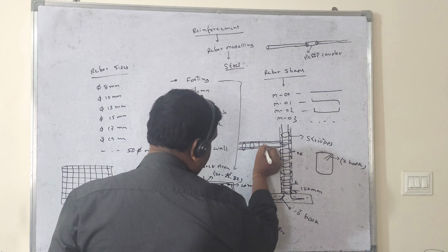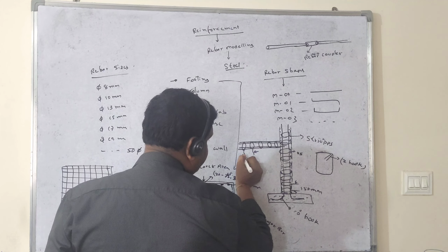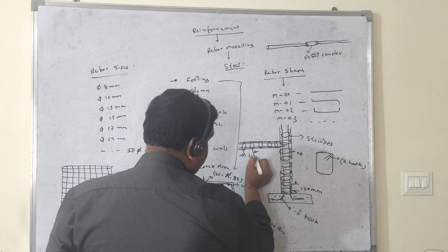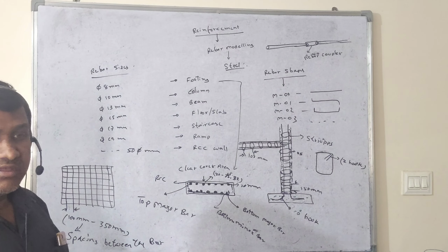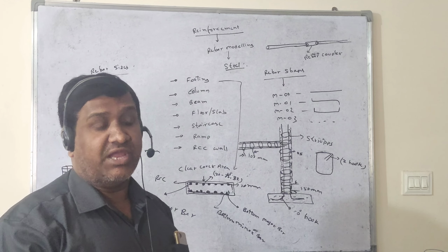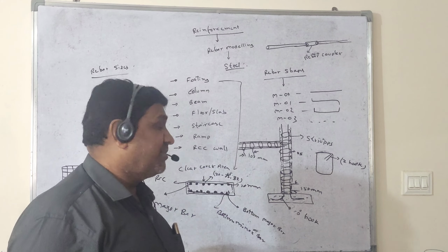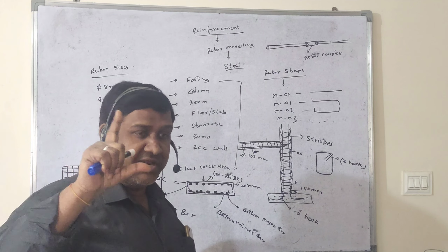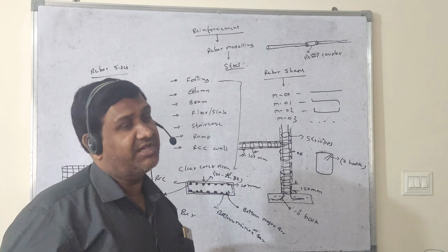So here if you place one stirrup, then for continuation we can provide the spacing, and it will become multiple stirrups at once. You provide one stirrup, and if you give the spacing, it will become multiple stirrups with the same spacing for the values you provide. So the stirrups are also placed here, like that.